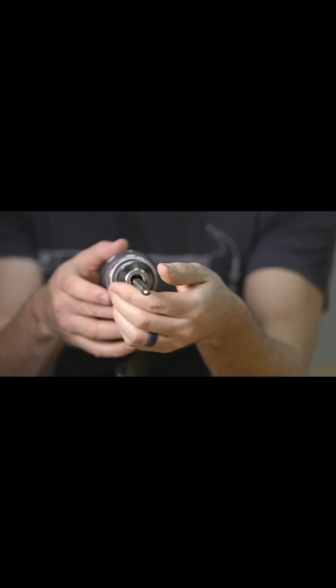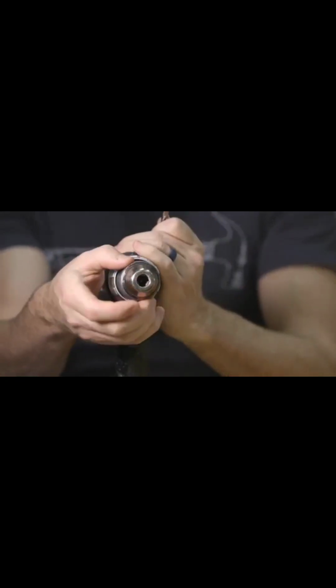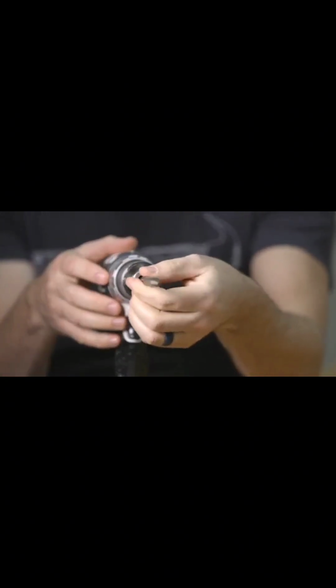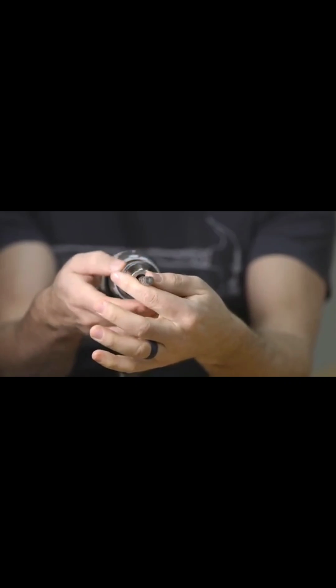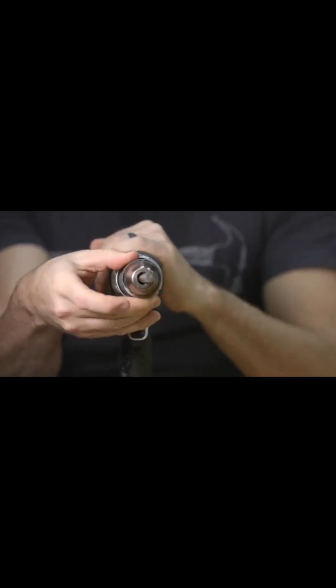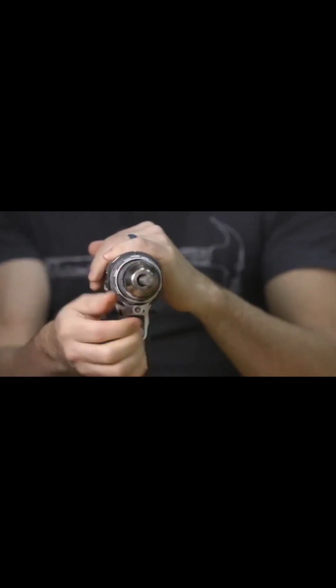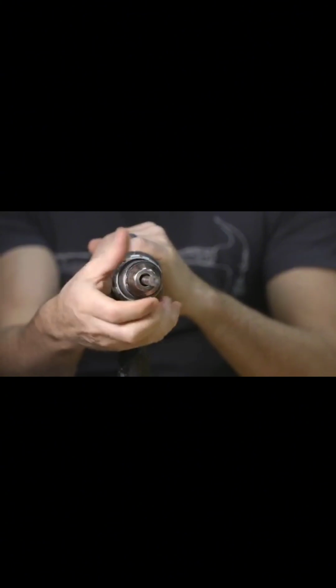There are countless drill and bit accessory options out there, which we'll get into in another video, but let's finish this video out by talking about a few techniques. First up is the techniques used to install and remove bits. For this particular drill, you can simply insert the bit, then rotate the chuck clockwise to tighten the jaws around the bit. Righty-tighty, lefty-loosey, as long as the drill is facing you.